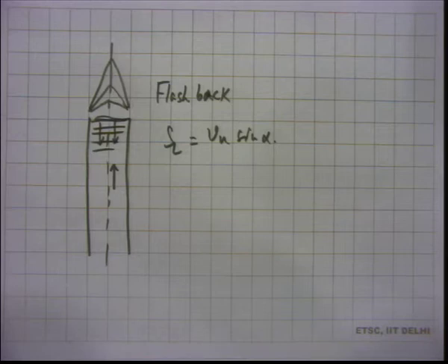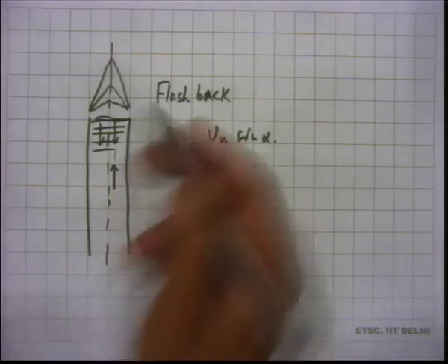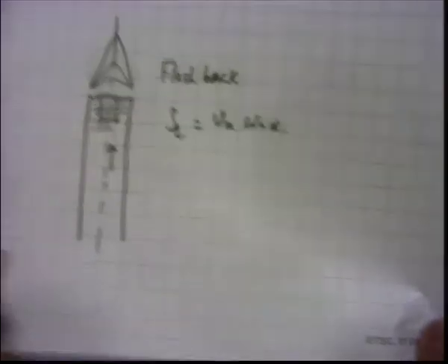We understood that flame is not a material surface, it actually heats the fuel air mixture ahead of it, and then also transfers some active chemical species to it, thereby ignites it, and thereby it moves. So, it will have a situation where it can easily move down because you are not feeding the fuel air mixture. This is what is happening. So, we understood that there is lift off, there is also blow off, and there is also flashback.